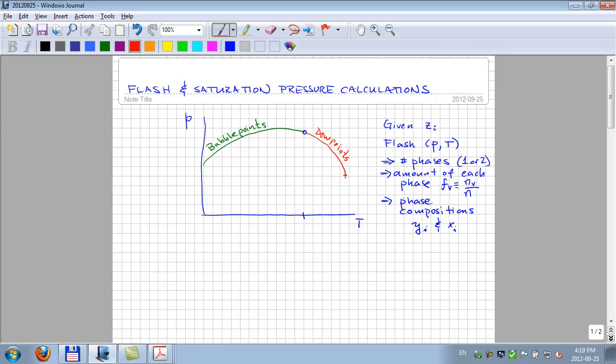And then we have another dew point that it starts finding, called the lower dew point. That curve will look something like this, and it'll hug very low pressures here and finally start increasing. So these are the lower dew points, and these are the upper dew points, where you have that composition being a gas phase with a small drop of liquid.